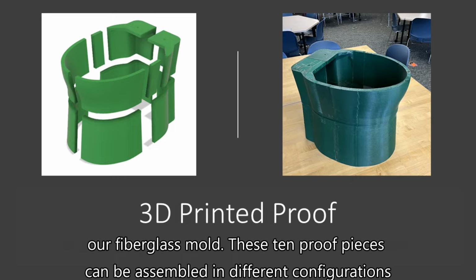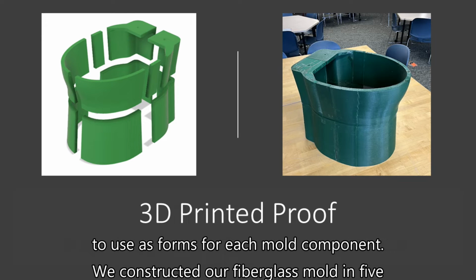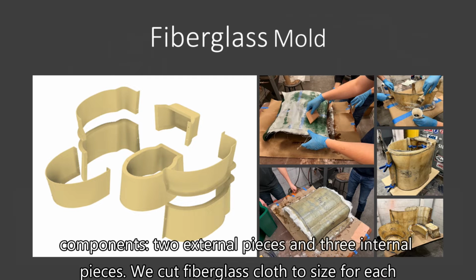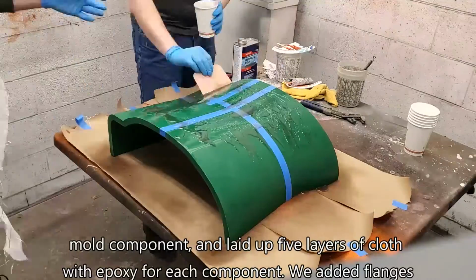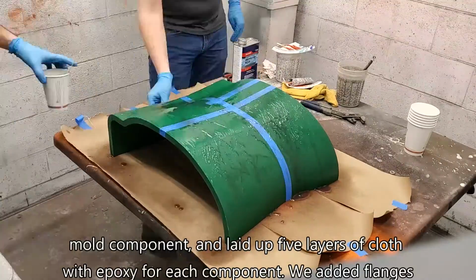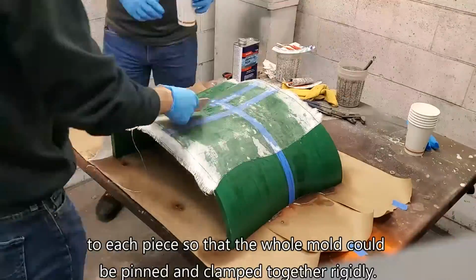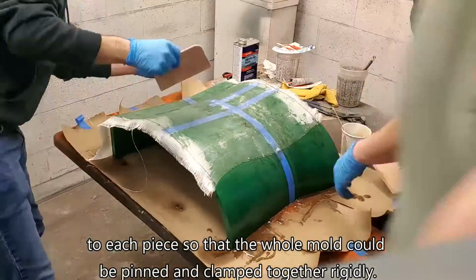These 10 proof pieces can be assembled in different configurations to be used as forms for each mold component. We constructed our fiberglass mold in 5 components, 2 external pieces and 3 internal pieces. We cut fiberglass cloth to size for each mold component and laid up 5 layers of cloth with epoxy for each component. We added flanges to each piece so that the whole mold could be pinned and clamped together rigidly.